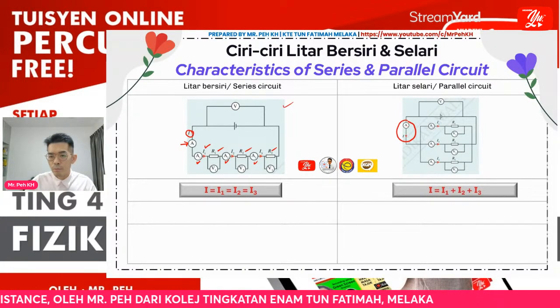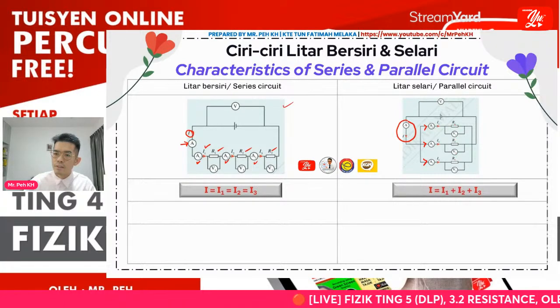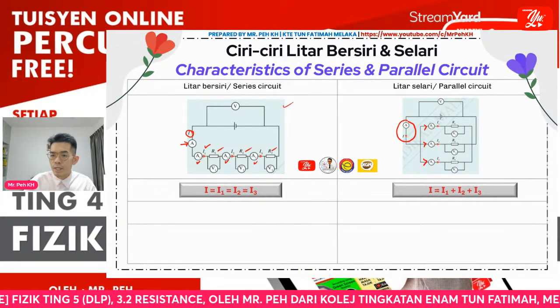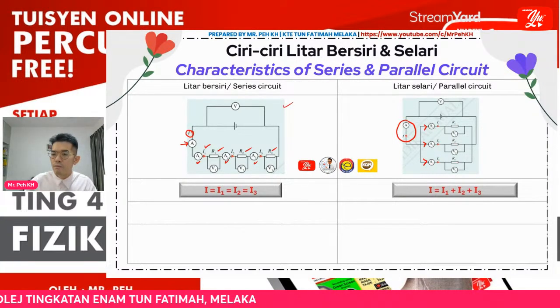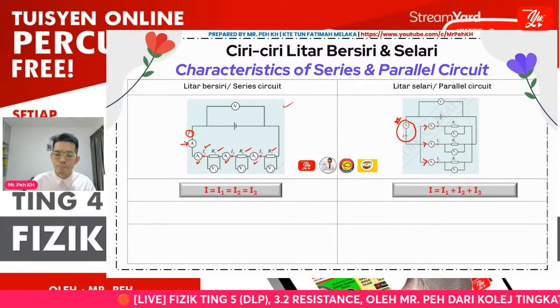Then for the parallel circuit, the I shown at the reading of ammeter A here will be the total current flowing through different routes. You can see R1, R2 and R3 are arranged in separate paths. So A1 will be the current flowing through R1, A2 the current through resistor 2, and A3 the current through R3. So I1 plus I2 plus I3 will be I, which is the reading of ammeter A here.